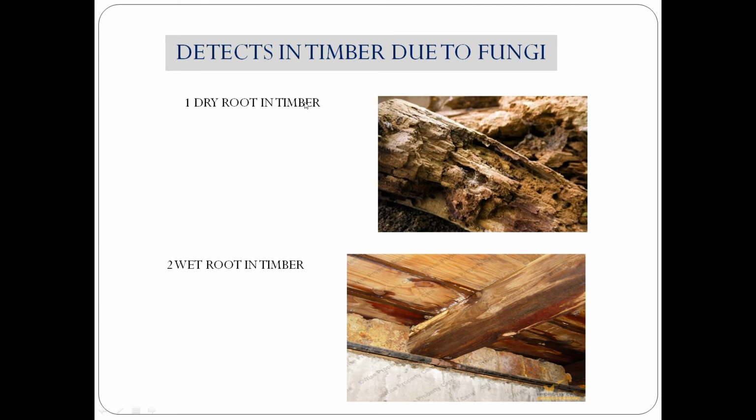Absence of sunlight, dampness, presence of air will increase the growth of dry rot causing fungi. This can be prevented by using well seasoned wood and also by painting the timber surface with copper sulphate.